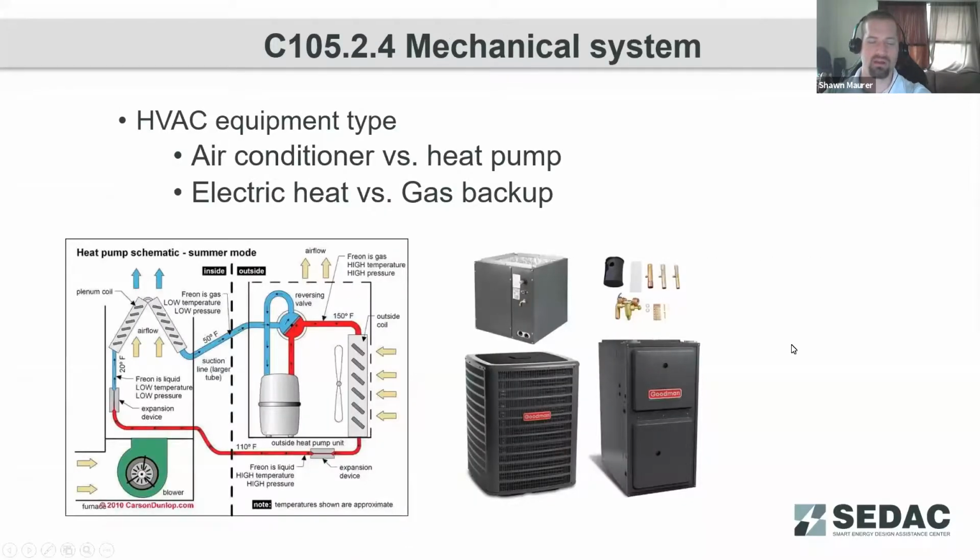One thing to be aware of is if your building is using heat pump equipment, this does add a little bit of additional complexity to your verification as you add that reversing valve control to the refrigeration system. So it's one more component that needs to be checked for proper operation.